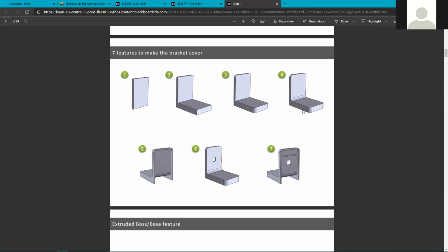The reason that you might do that, just as a little aside, is that if you create injection molded parts and you leave quite thick wall sections, like figure 4 here, as the part cools, the outside obviously cools first because it's more open to the surroundings, and the inside stays partially molten for longer. And then as the inside cools, it tends to drag the outside surface inward. So you get a little impression, a little dimple, known as a sink mark. So that's why you try to thin out a lot of the walls like this.